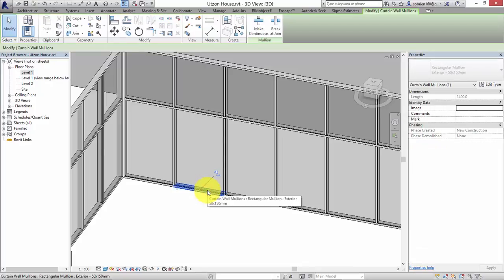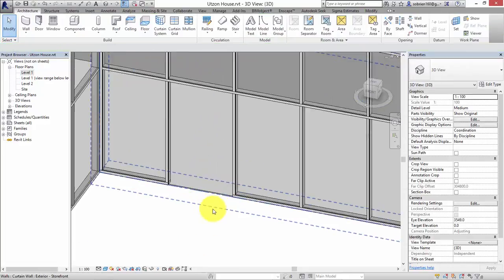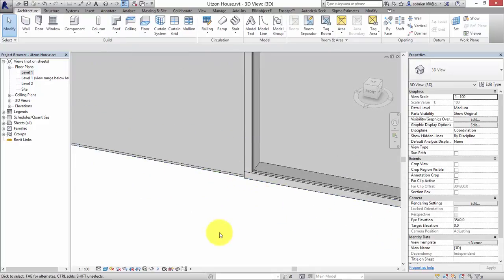We don't have to follow this very methodical layout. So if I click that and select it, we get this little pin turning up. The pin tool usually means in Revit that something is stuck down. It's been stuck to the floor, and you can't change it until you take the pin out. So I'm going to click on the little pin here, and that means the pin has been pulled out. If you get something where the pin is sideways and has a little red X on it, the pin has been pulled out, and that element of the model can be modified. So then I can just delete it. Now we've got no frame in that area, just a piece of glass that goes right down to the floor.